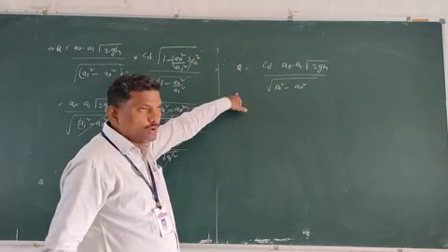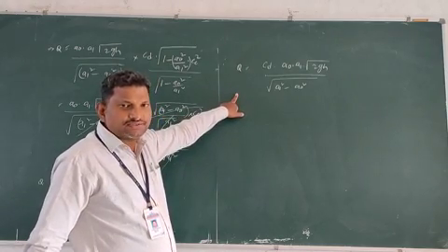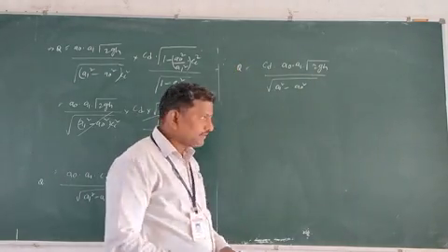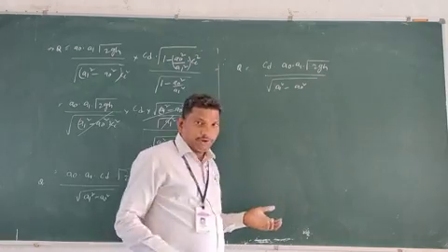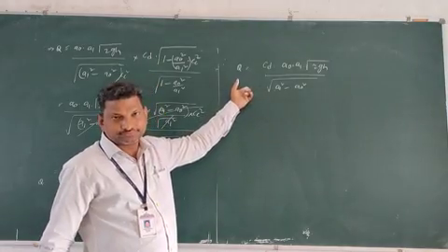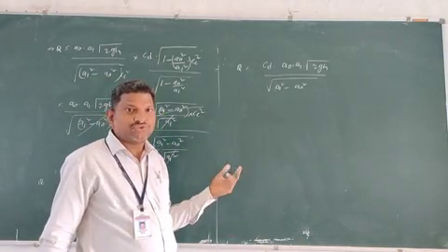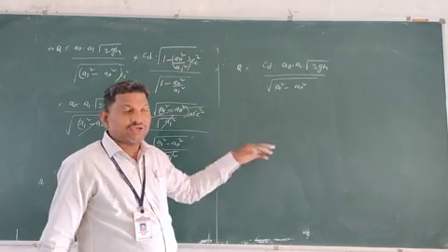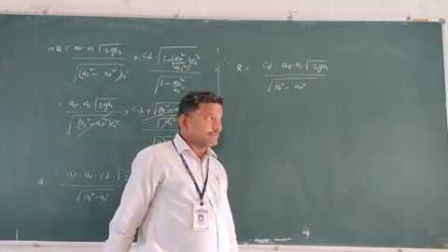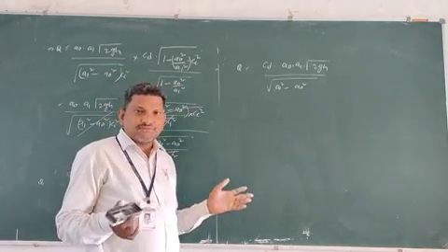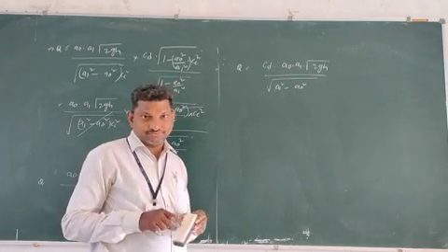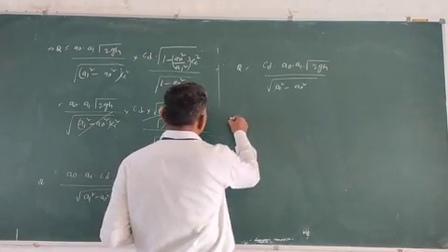But here there are no terms of Cc, only coefficient of discharge terms. Okay, in any problem, if coefficient of discharge is given, use this equation. If coefficient of contraction is given, use equation 4. Understand? Okay, so by giving the various values, we can find out the required values.